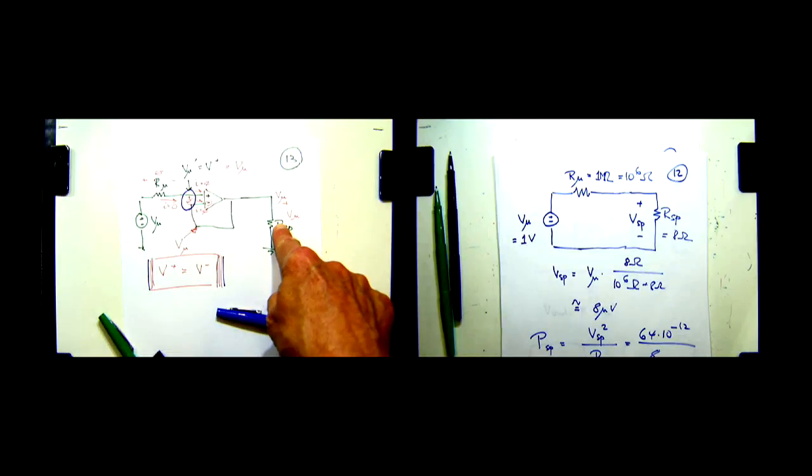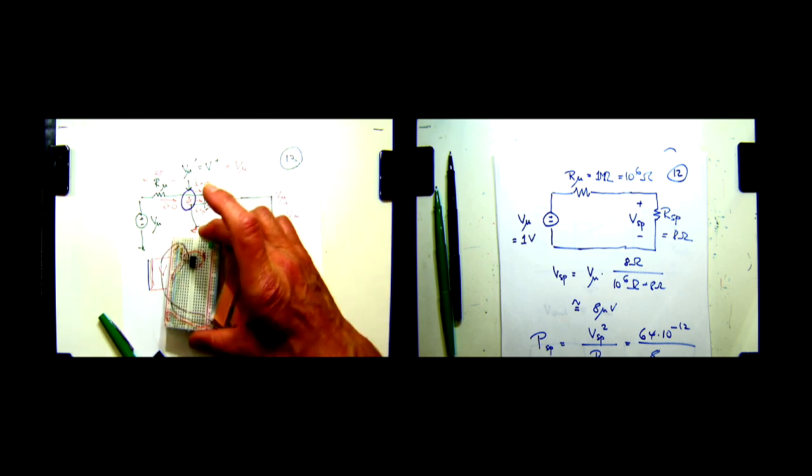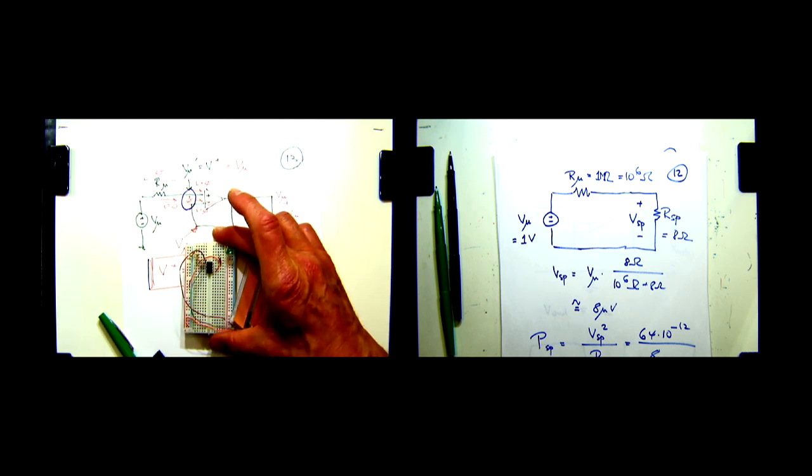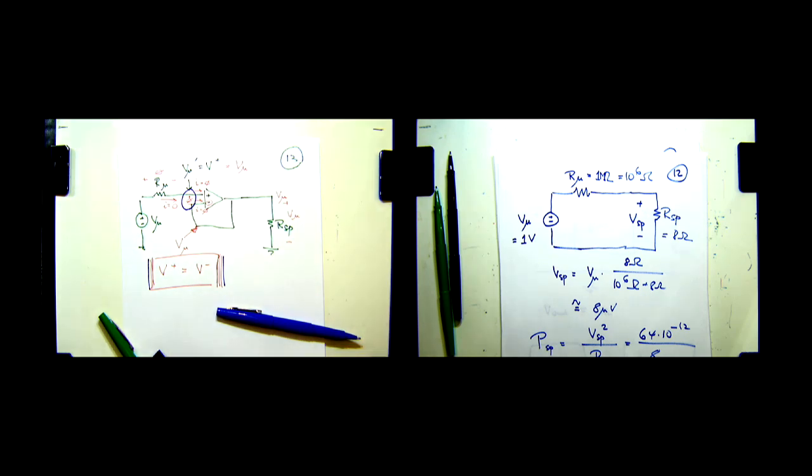Okay? So the other thing is kind of obvious, that this is an ideal operational amplifier, and therefore we could deliver 1,000 amps or whatever is required to this resistor. That little operational amplifier here, do you think it delivers 1,000 amps? No, just like any practical component. This operational amplifier is probably going to be ideal in the sense that it can deliver currents up to maybe 100 milliamps, okay, 0.1 amps. Beyond that, it just shuts off. There's a protection circuit built into it so that instead of going into operational amplifier heaven, it simply turns itself off, okay?